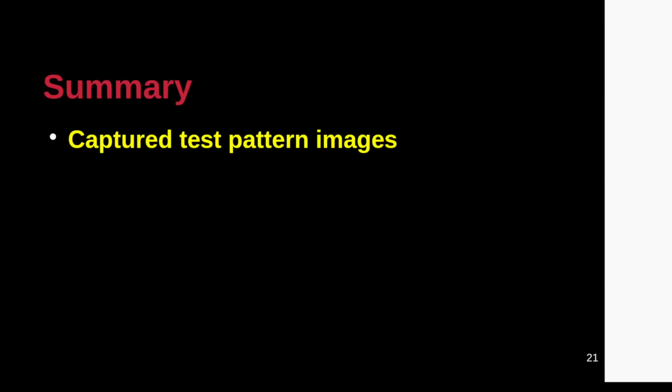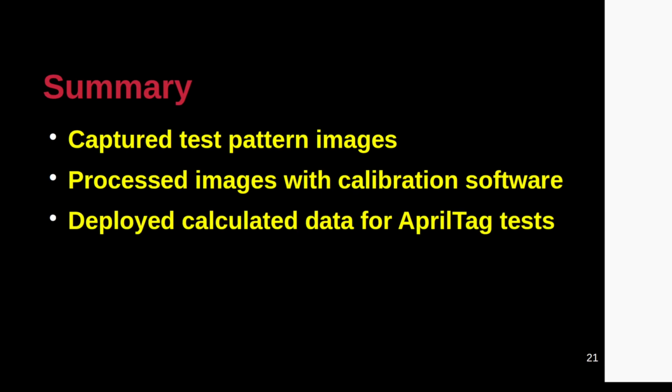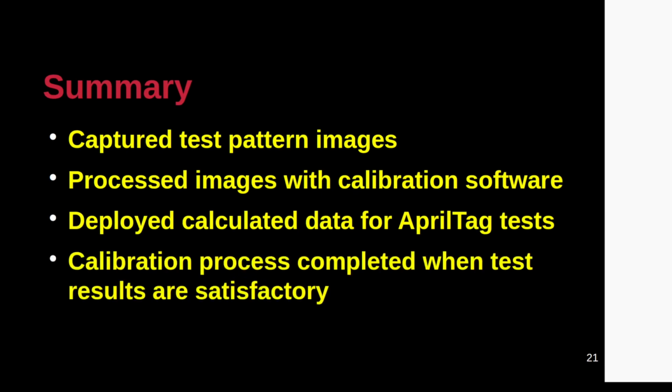This tutorial introduced camera calibration for First Tech Challenge robots. The FTC SDK has an example OpMode to capture images. This OpMode and a standalone Python script were demonstrated for the acquisition of images from the camera that is undergoing calibration.